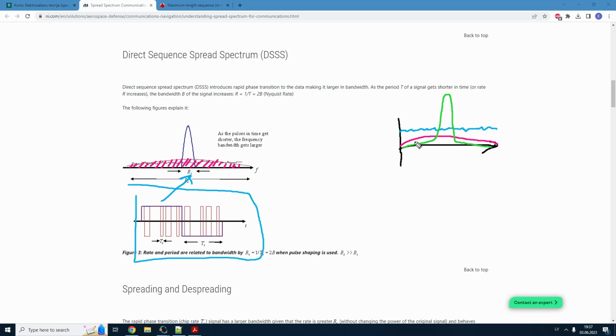Well, this is nothing for white noise, because white noise already has an infinitely large spectrum, but if you were to fight some unwanted, or intentional, jamming of your signal, which would normally try to jam part of your signal spectrum, then this artificial jamming signal, after this operation, would act as if it were spread, and it would minimize its effect on your signal. So this is very important for military use, where you try to jam signals or, vice versa, to not be jammed.